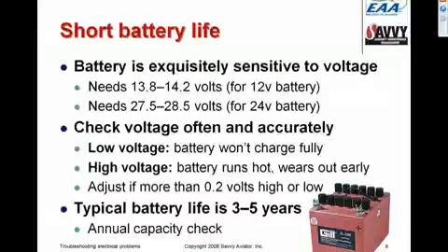And that will be bad if you have a charging system failure and wind up operating on battery only, because if the battery hasn't accepted a full charge, then you will have less time to get the airplane on the ground than you should. So we don't want the bus voltage to be lower than spec. But even more importantly, we don't want it to be higher than spec.